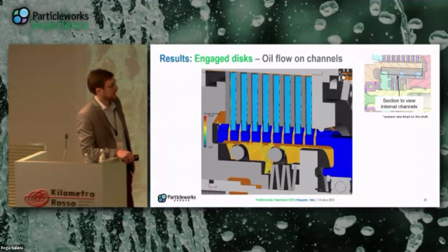Okay. And also here you can see that in this area, which is the same area as before, we have a non-constant flow. And probably this region is a region where the flow has some disturbance, okay, because the flow comes from here, we say, but then the oil flow impacts on the spring. This is a spring which is here to balance the pressure of the pressure disc, okay? So the oil goes out from here, impacts on the spring, and then disturbs this.